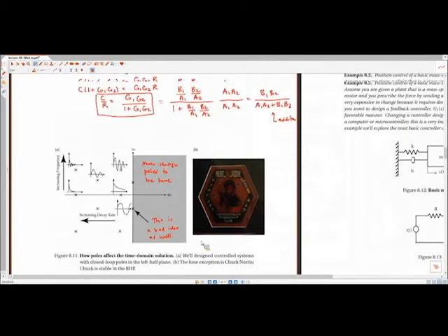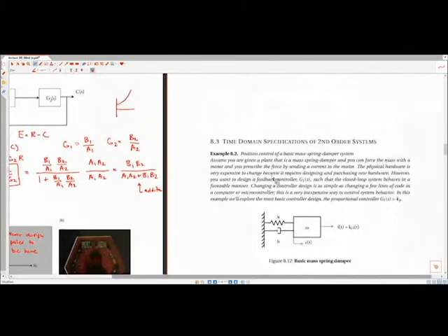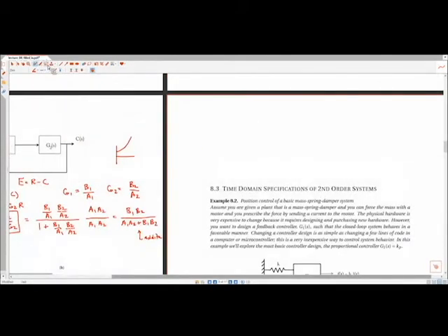Okay, so just to give a general idea of what we're talking about here with a controlled system, what this allows us to do. Because this allows us to start to move around the poles of the system, the C over R, we're changing the pole locations, we're changing the basic fundamental characteristics of the system, right? So by changing the pole locations, what this allows us to do is make a slow system fast. If the plant naturally has poles that are close to the origin, so they correspond to really slowly decaying exponentials, we can move them such that it acts in a faster way.